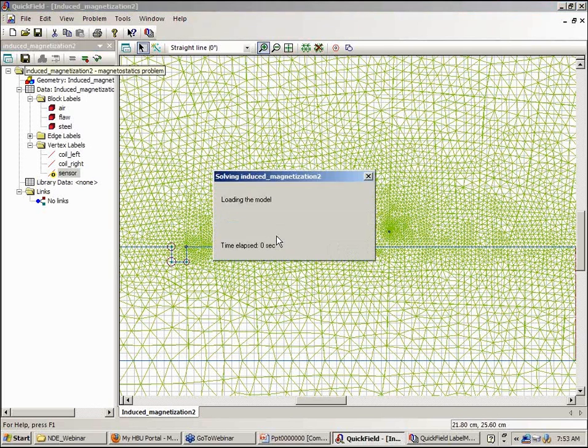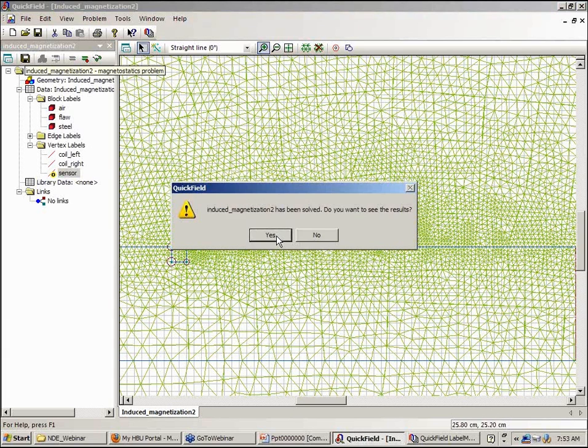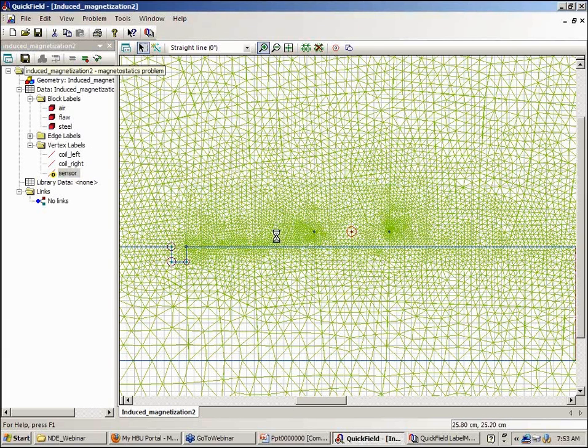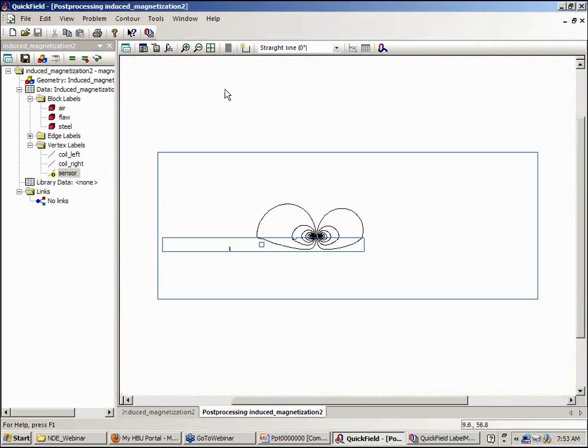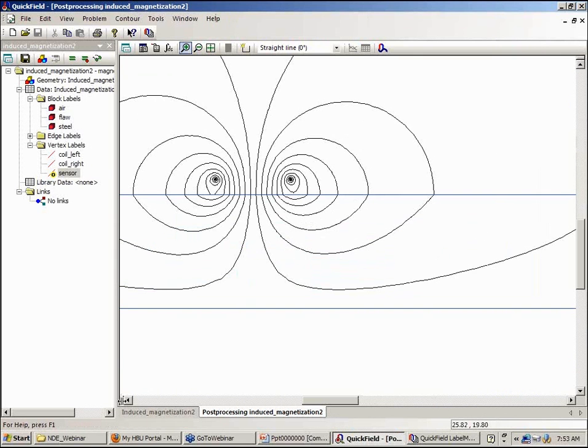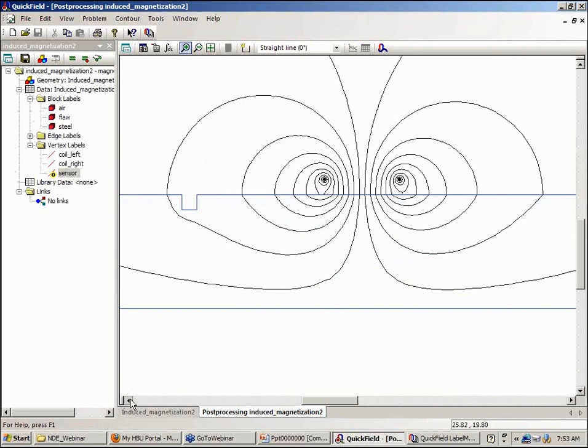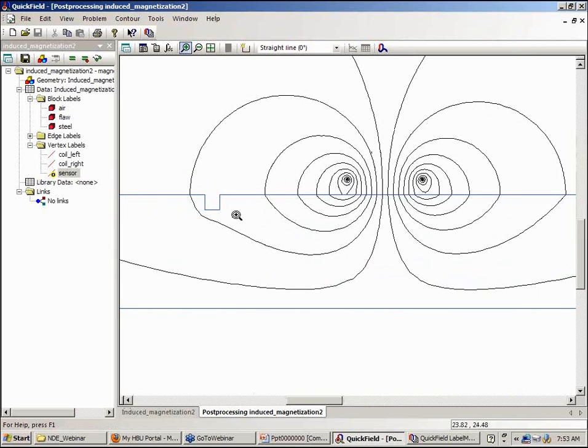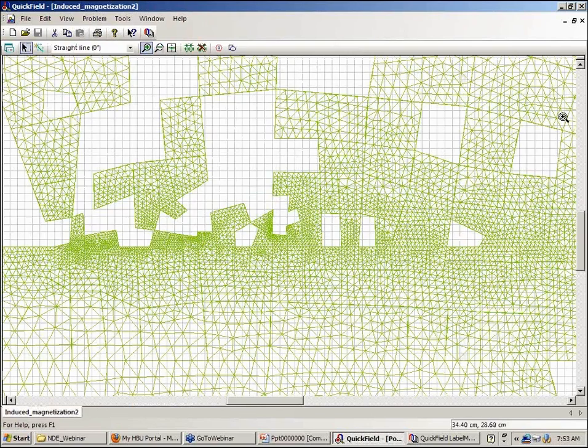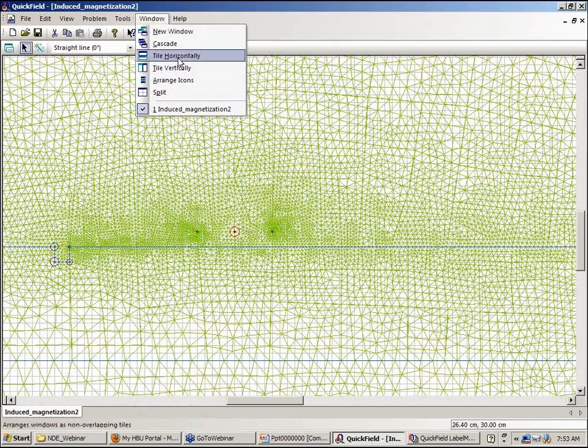So we'll just look at the field distribution. And this is the DC magnetic field, DC magnetics. You can see that the DC magnetic field is going to be perturbed by the presence of any defects. I want to illustrate the ferrite needle concept for improving the spatial resolution.